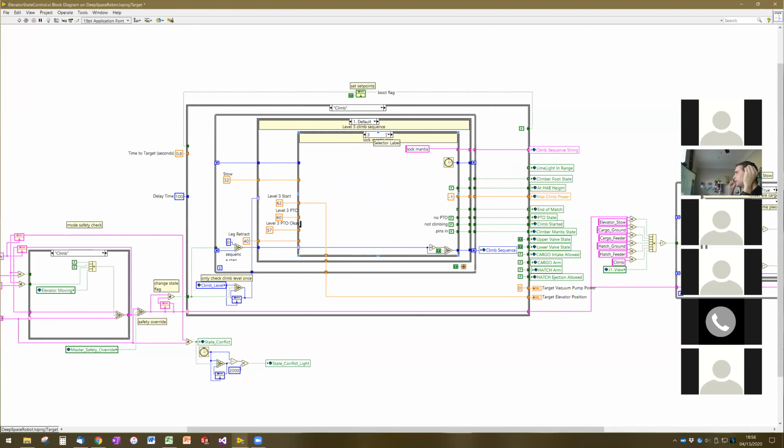In this step, the pins for the mantis arms extend again to lock the mantis arms in place and keep them from ever folding back up into the robot while we're climbing. And we also start another timer. There's something after this that also needs a timer, and so we have to start a new timer so we can measure the time off of this step versus some previous step. So the second timer is waiting 500 milliseconds for the pins on the piston to fully extend and grab onto the mantis arms.